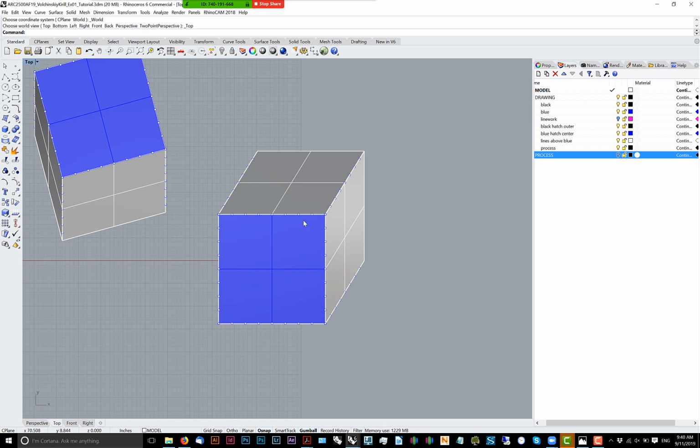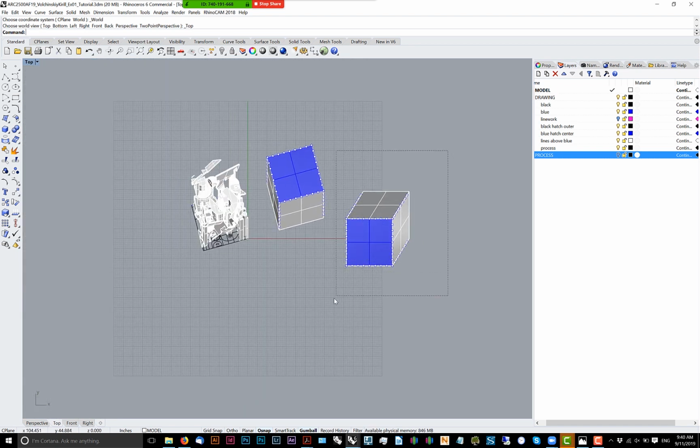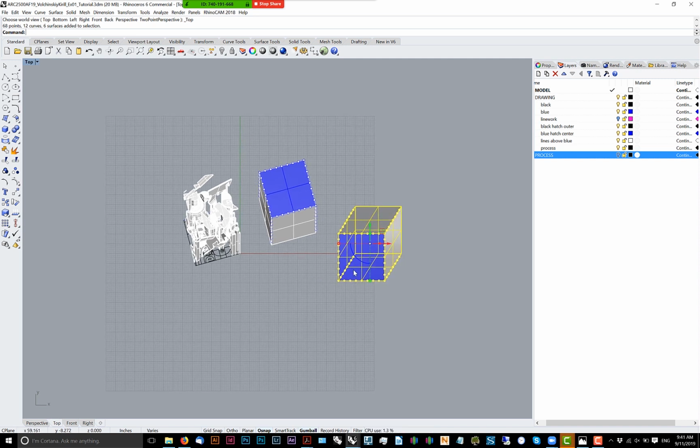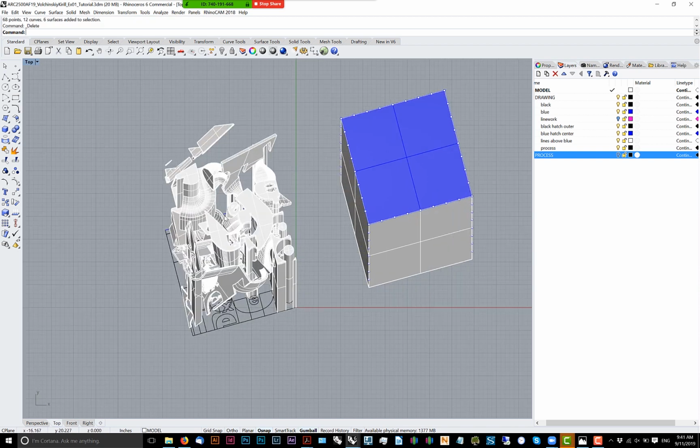So, does anybody recognize it? Kind of. Do you remember? Okay. But what I'm trying to explain basically is using the shear and rotate command, you can achieve any kind of projection in Rhino as you're projecting onto the C-plane, top view. So I recommend everybody to just take your geometry right now and try applying one of these transformations to it. So again, you can shear in the top, right, or front viewports. Just play with it. Get something that you like.